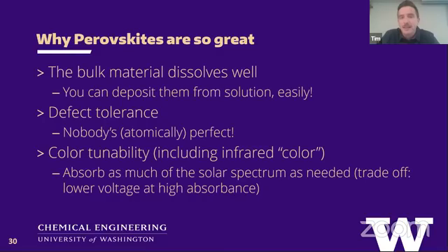And then finally, color tunability. For those who are more technically inclined, I'm talking band gap tunability here, but the ability to tune the infrared color of the perovskite solar cell means that, while I can't see a difference in color with my eye, I can use the change in infrared color to make perovskites fit into a variety of different applications that wouldn't be accessible to a semiconductor like silicon, where you only have one color of material.